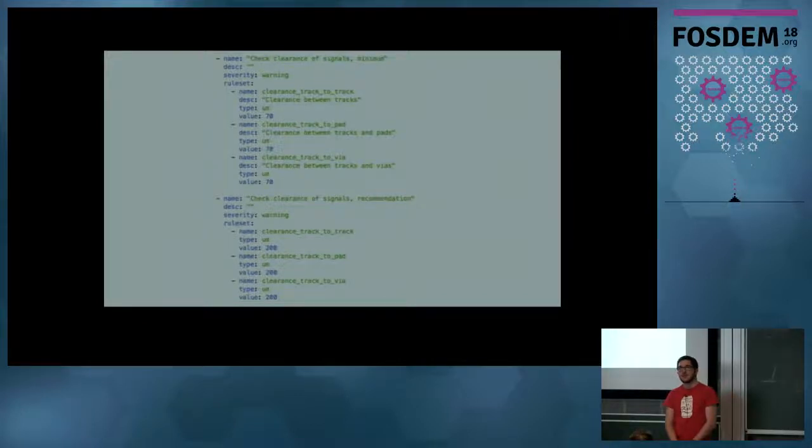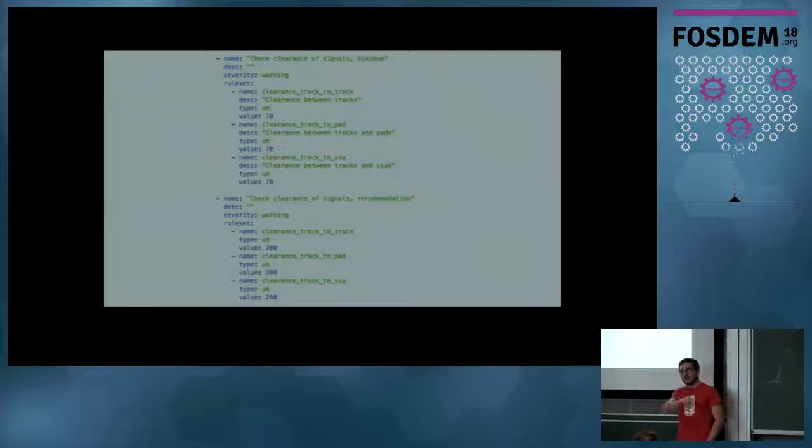This is important for the checker, which must take that into account. That's totally correct, but it does not apply for the manufacturing. For the manufacturing, I just don't care how much voltage there is. Maybe the idea is to take this as the foundation and then add some more design EDA related stuff on top of it. But you do care about outer versus inner layers. You have different clearances. So that's the same thing.